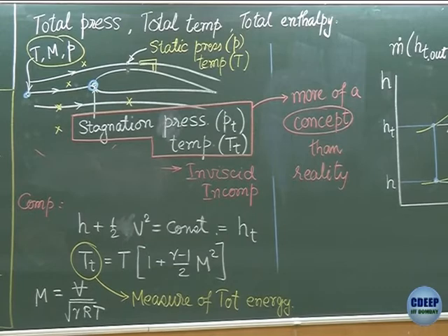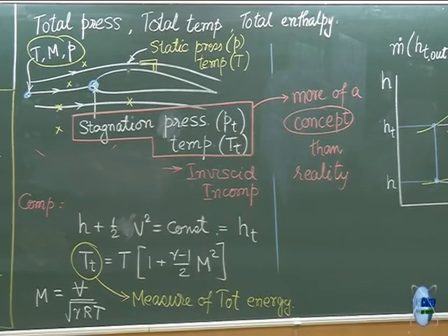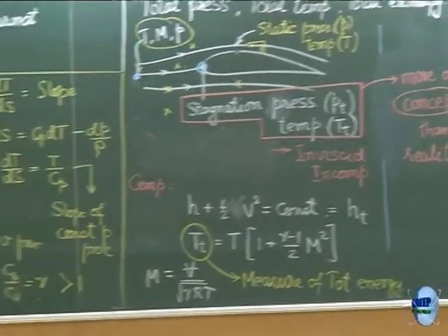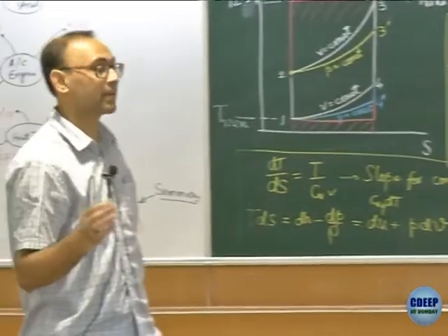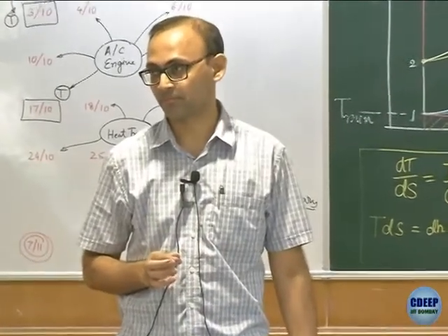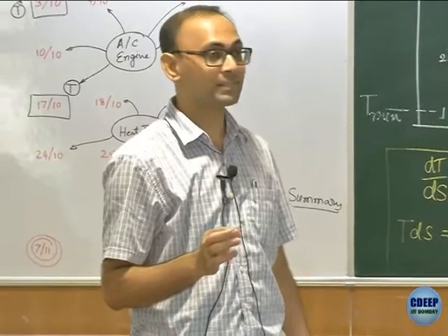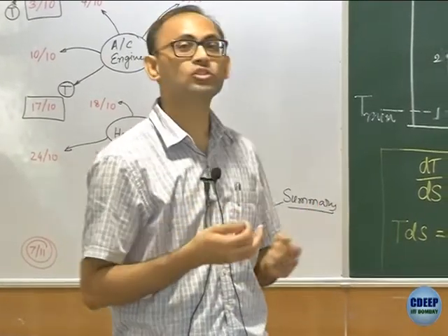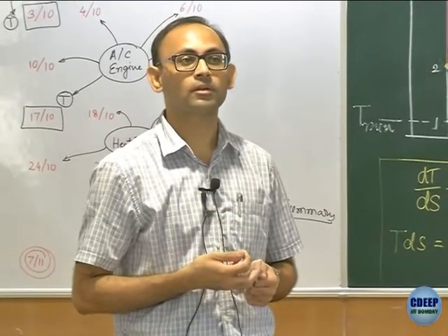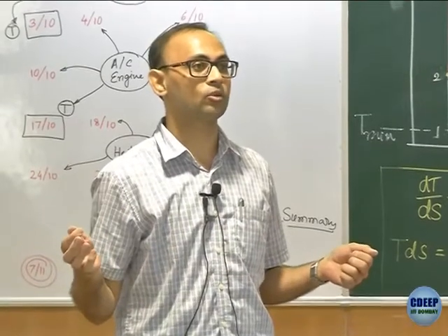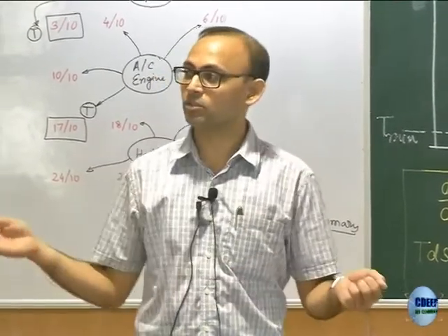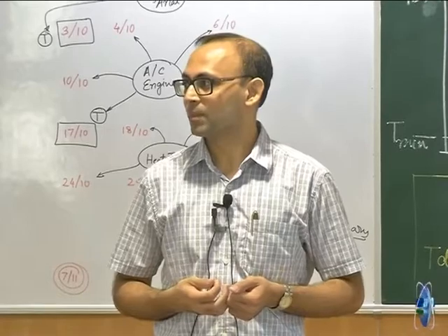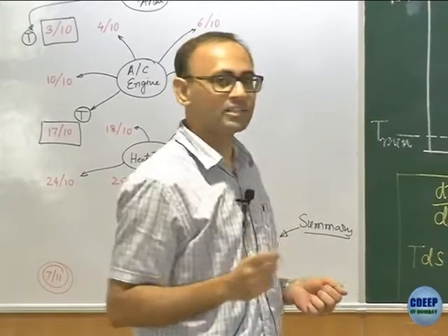The flow may never really come to a stagnation point, but we don't need the flow to come to a stagnation point to get its stagnation pressure and stagnation temperature. These are ideas which represent the total amount of energy in the flow. You don't have to bring it to rest to get that energy. You don't need to measure it. You know the velocity and you know the temperature, you can get its value. But that total temperature is really important.